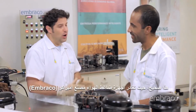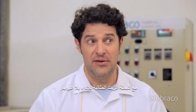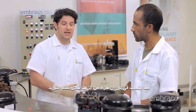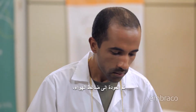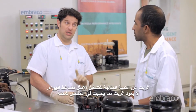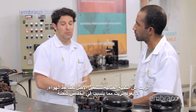It's true. Compressors leave Embraco's factory with the ideal oil charge for flawless performance. What happens is that during the cooling cycle, the oil mixes with the refrigerant fluid, causing a fraction of the oil to circulate through the cooling system and back to the compressor. But when there's an obstruction in the tubing or problems in the system's sizing, the oil can't return, causing the charge to be less than ideal for the compressor's optimal operation.